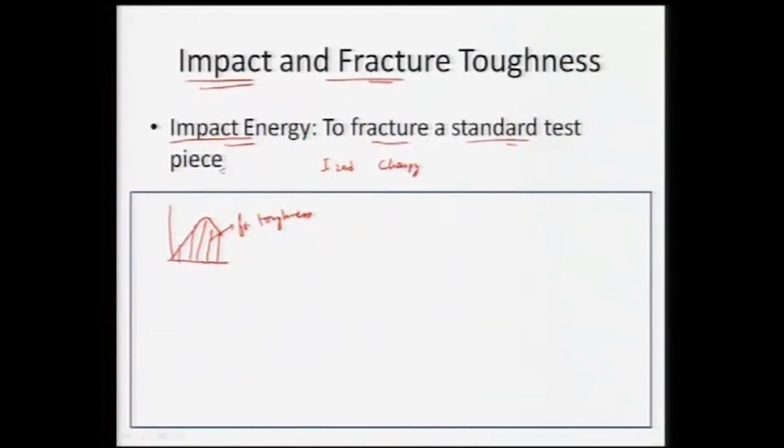In this case, what is happening is we develop a notch in the material, and that material is now supported on these two ends, and an impact is provided on the other side, and then this material entirely fractures. That particular sample has also been tested using Charpy, using this instrumentation.